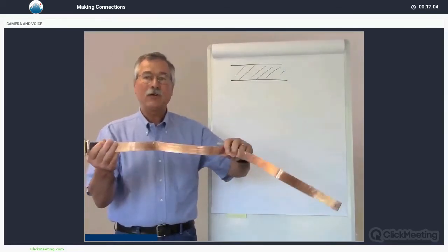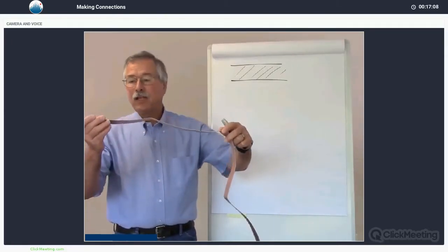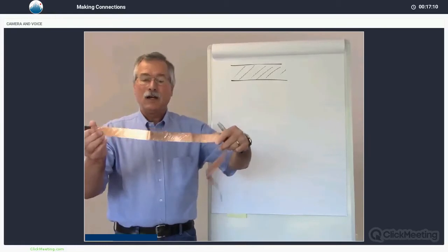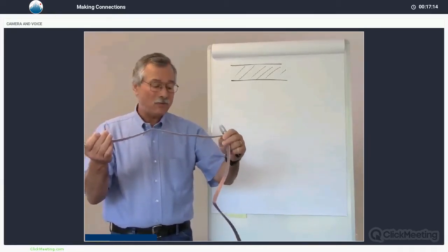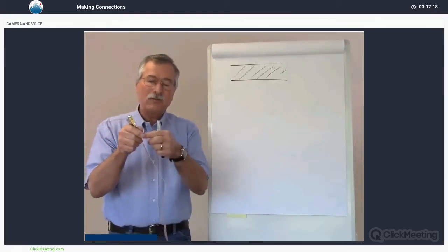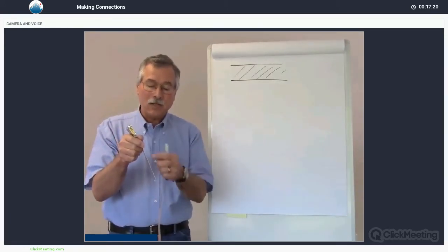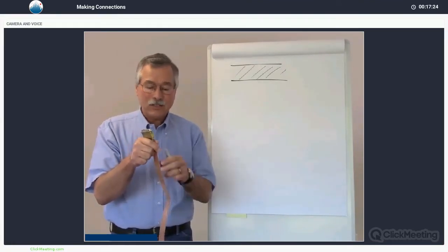It's made out of very heavy copper. And there's actually two conductors here. They're thin. They are kept close together. However, we try to keep this as symmetrical as we possibly can. Why? Because the current going out from the driver to the laser diode on one conductor generates a magnetic field in one direction.